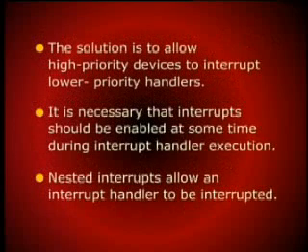The solution is to allow high priority devices to interrupt lower priority handlers. An interrupt handler is just a program, and as such, its state can be saved and restored to allow it to be resumed where it was left off. It is only necessary that interrupts be enabled at some time during the interrupt handler execution. A system of interrupts that allows an interrupt handler to be interrupted is known as nested interrupts.